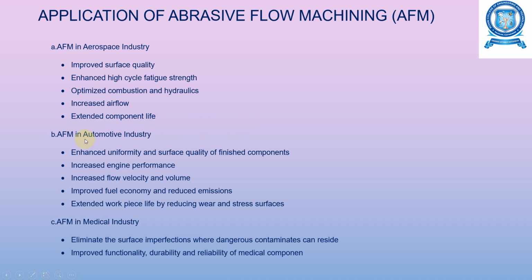And in automotive industry, abrasive flow machining can be used to enhance uniformity and surface quality of the finished components, increase engine performance, increase flow velocity and volume, and fuel economy is improved and the emission is reduced, and the workpiece life is extended by reducing wear and stress surfaces.